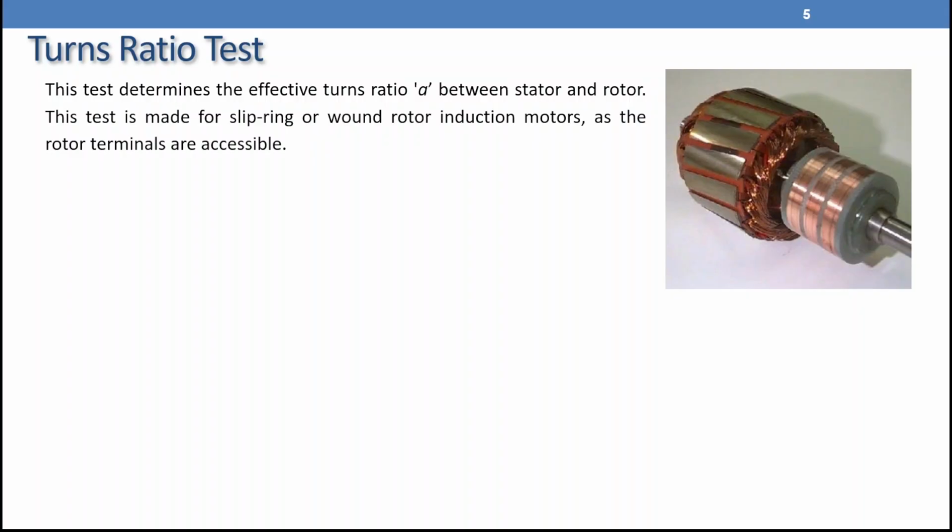We cannot access the rotor of the squirrel cage, so the squirrel cage is another, more complex analysis, but for the squirrel cage we can calculate the rotor impedance referred to the stator side from the stator test. For this machine, we sometimes need to know the effective values of the rotor impedance in the rotor, because this machine could be used as an induction generator for wind turbine applications, as an example.